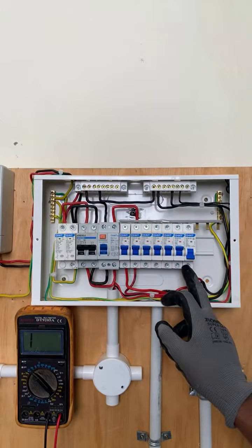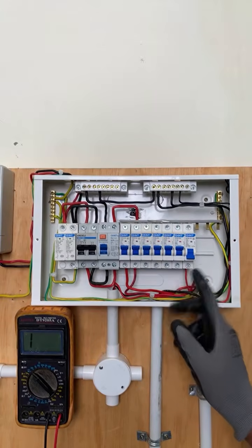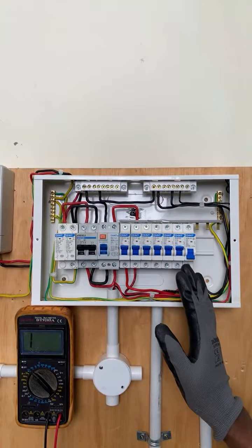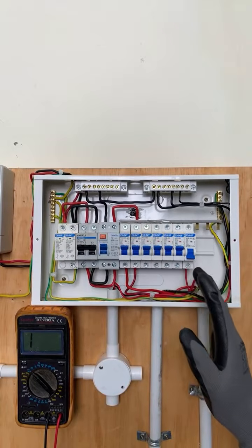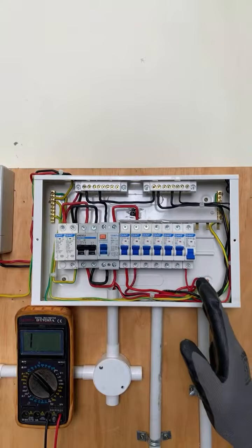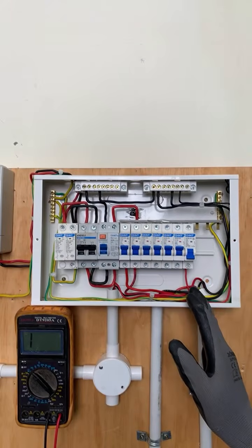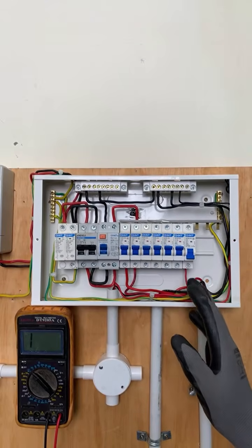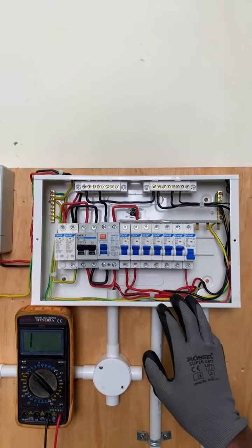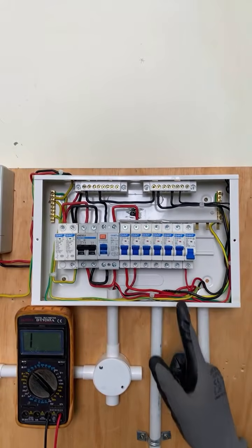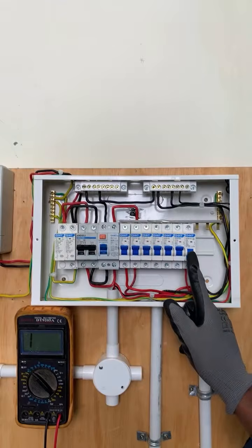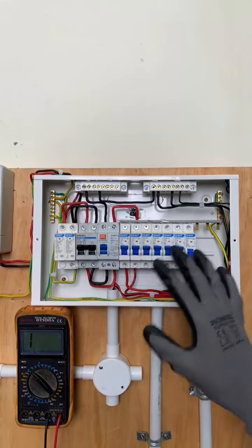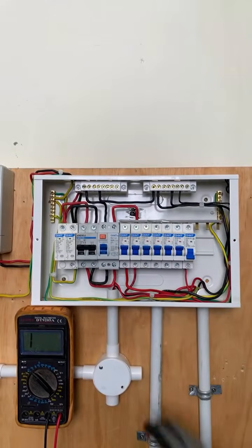Okay. Number one reason could be there is a short circuit in that line. Either one bulb in the corridor or the light in the kitchen has a short circuit, or if it is on the balcony or the dining section, there is a problem there. That is why this MCB tripped, and it cut off the supply of current to those areas that I've mentioned.